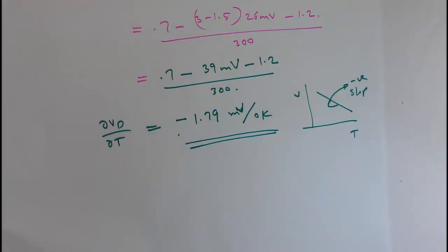That really depends on the voltage across the diode, that is the Vd term, and in the textbooks that was given as minus 1.6 millivolt per degree Kelvin. Then when we made the circuit of the BGR, we found that actually the current through the diode is not a constant, it is a PTAT, and then we modified all our equations assuming I0 is a PTAT.